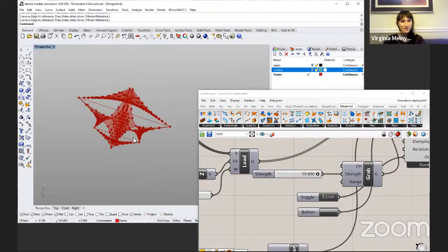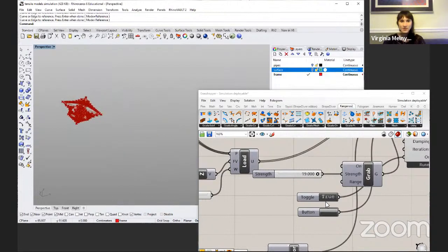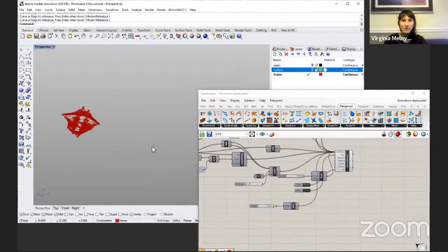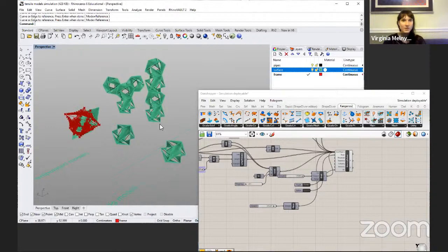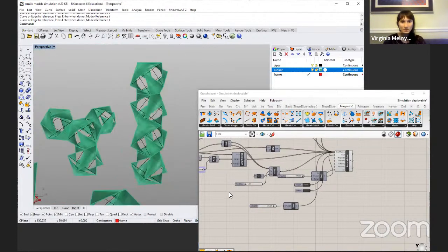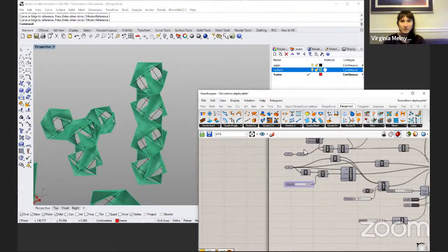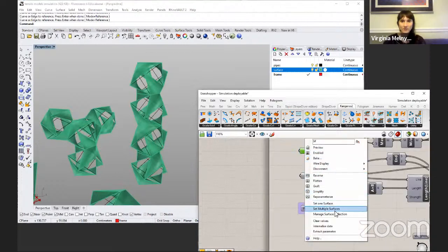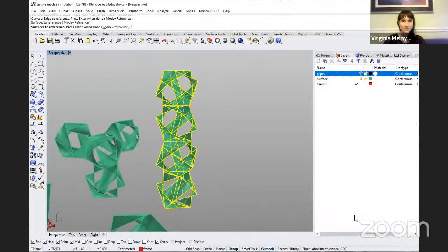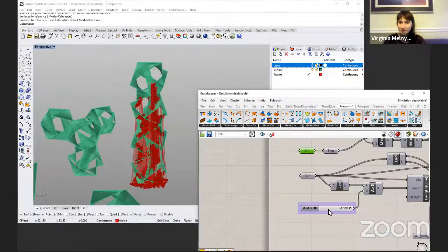And we can do the same thing, as you see in the definition, if I turn back on these cluster ones, like if I wanted to create a tower here, I can select all of those surfaces. So right click, set multiple surfaces, and I'm going to hide those for a second and select all these surfaces, and watch it fall to the ground until we get our sticks.